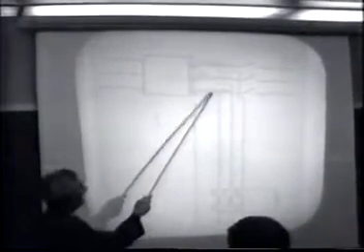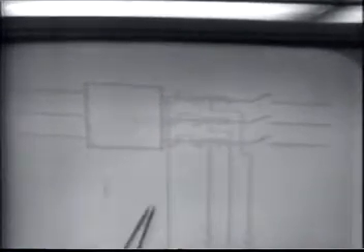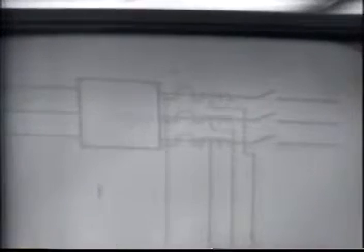There is the metering current transformers, which were shown just as a single component on the one-line diagram. But since this is a three-phase circuit, we of course have three transformers, one on each of the bushings of the circuit breaker. There was some identification left off of this sketch, I see.